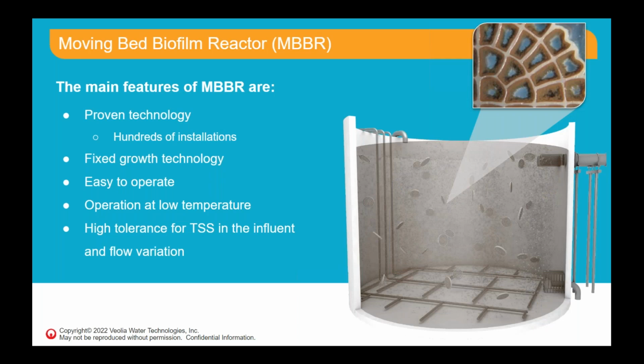It's the moving bed biofilm reactor. The main feature of the MBBR is that it's a proven technology. There are hundreds of installations for nitrification, denitrification, COD removal, BOD removal, and some exotics. There's some selenium removal, biological, traditional selenium removal using an MBBR, thiosalts, a couple of applications. It's a fixed growth technology.